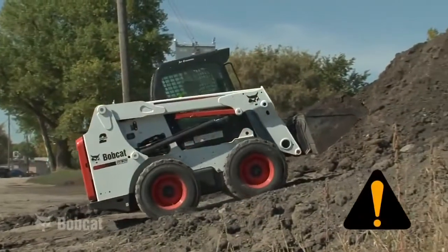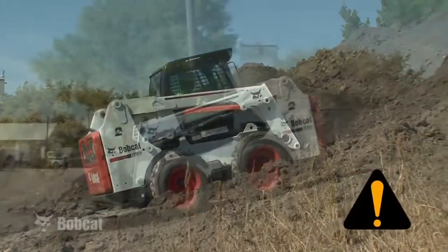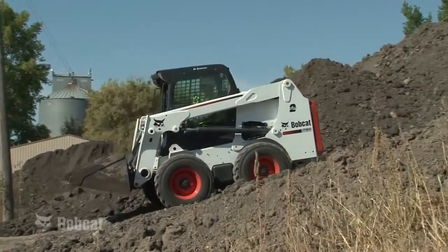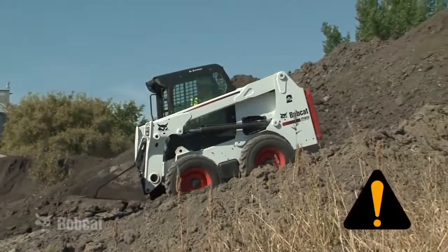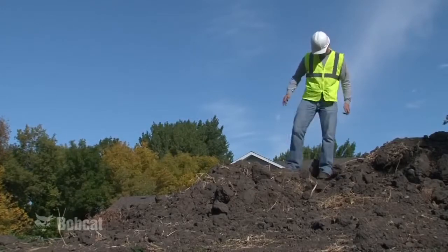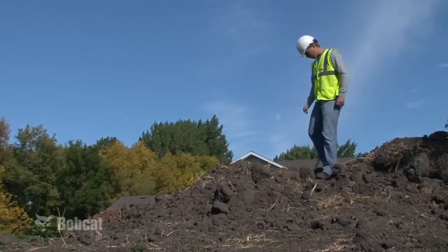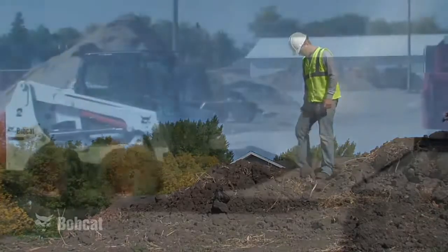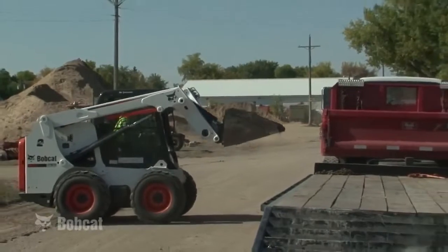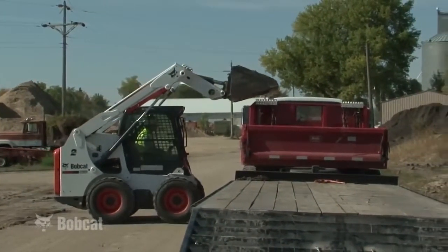Drive straight up or down slopes and keep the heavy end of the loader uphill. With no load, the rear is heavier. Refer to the operation and maintenance manual for specific instructions for your loader. Always check the surface conditions for adequate traction to avoid sliding down a slippery slope, causing a rollover. Slow down as you approach the dump site. Raise the load slowly, keeping your load level to prevent spilling over the back of the bucket.